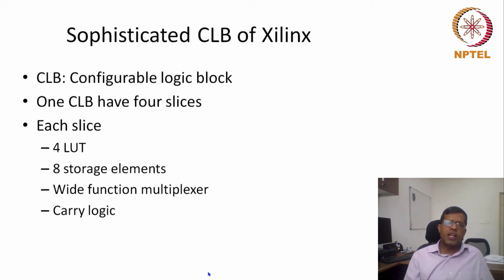So you can see that one configurable logic block is tightly connected. There are a lot of hard wires, so it doesn't require so much configurable interconnect. This CLB has essentially 16 LUTs and 8 times 4, 32 storage elements, and also a carry logic.